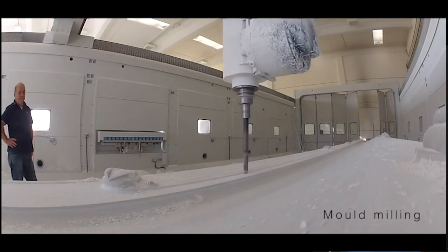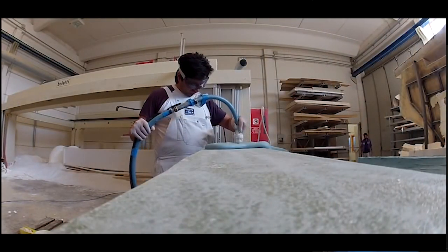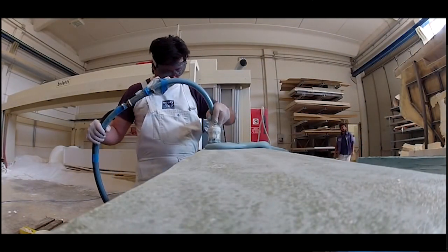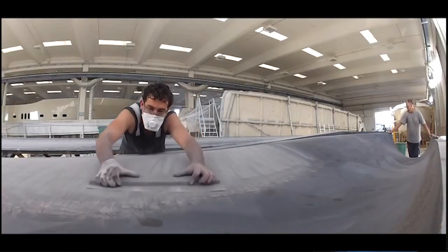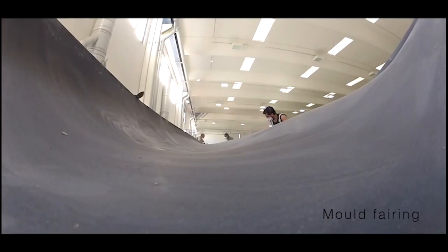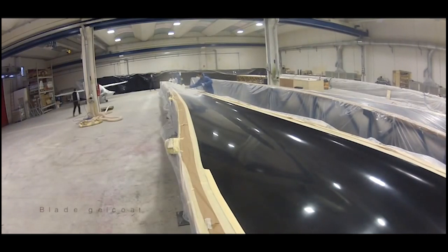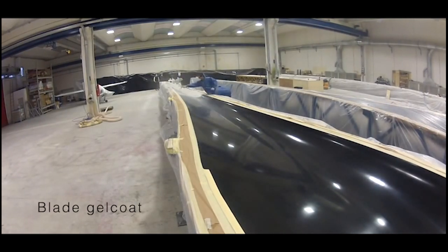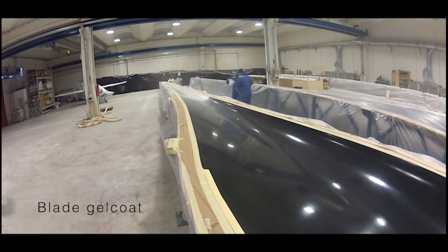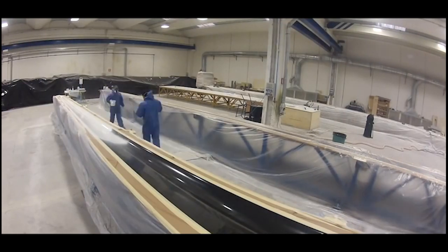First step would be the fabrication of the mold. There needs to be a shape, a rigid shape. Usually it's milling, it could be in different materials. Finishing of the mold, called fairing, actually involves quite a lot of manual labor to get a perfect finish. The finish of the mold would be the quality of the part that we are manufacturing.